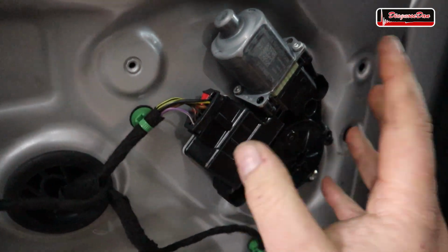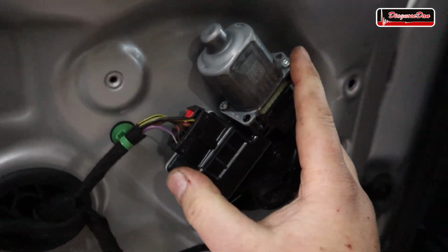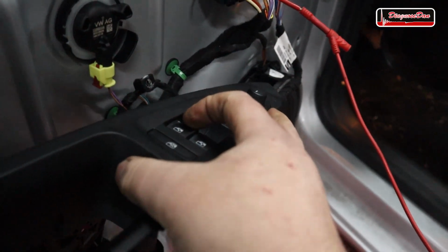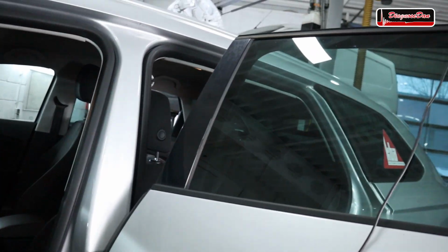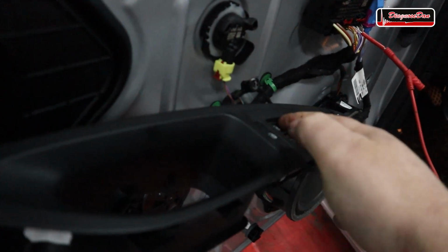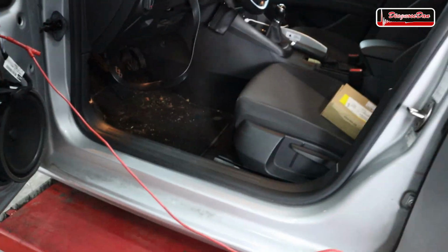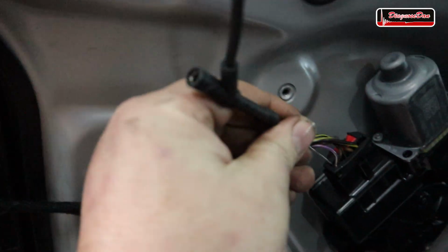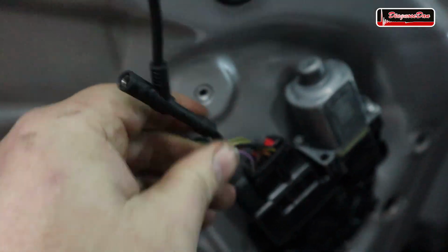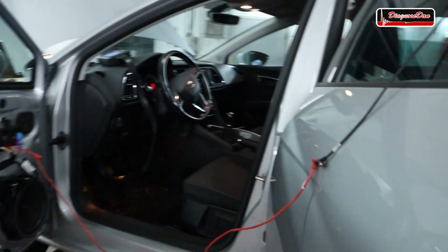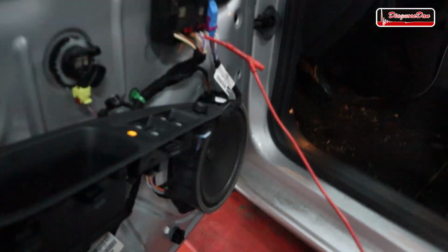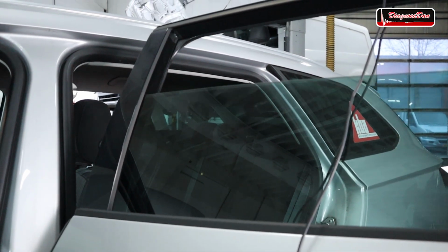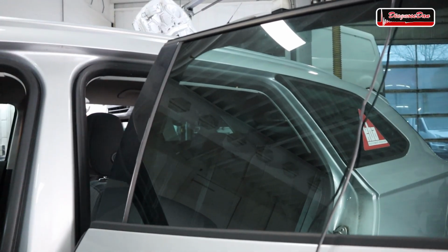I reinstalled the original module, or the original window regulator from this vehicle, which is probably fine. Now let's find out what happens when we're trying to open that window right now. When we're trying to open that window, it still doesn't work. And my light is, oh, of course, we do have to connect our homemade communication wire. There we go. So right now we've got a direct line between that module and the one in the front. Light is back on. Let's push the button and voila, there we go. The window opens and closes again.